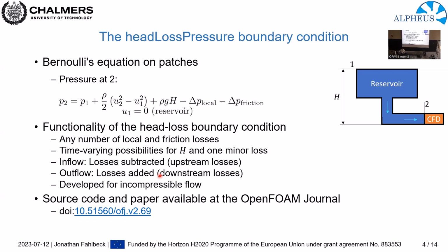The question was if there are any advantages of using the k-omega SST SAS compared to the k-omega SST. The simple answer is yes, because with the SAS modifications, you allow for a decrease in the turbulent viscosity, so you actually resolve part of the turbulence in the numerical domain. But this is done automatically via a function, so most likely you would like to verify that the SAS model is appropriate for your case. In general, you will get a more accurate solution using the SAS simulations. I also tried running simulations using only the SST model, and I don't like what I see, if we put it that way.